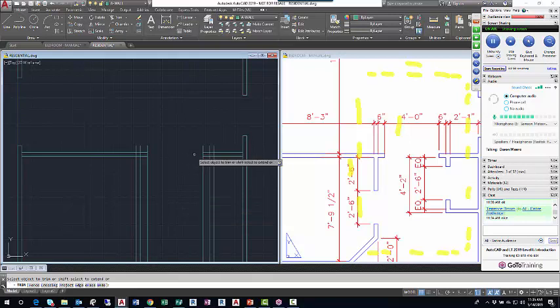I'll left click this vertical line that extends down below the wall I'm making. Left click. These 3 lines that protrude above the wall can go away. Left click, left click, left click. All right, and then the lines that are inside the wall, if you look at the markup, it's very hollow in there. The trim command allows me to get that hollow look. I'll do where the horizontal lines meet the vertical too. There's that hollow look. These cleared out wall looks are called wall intersections.